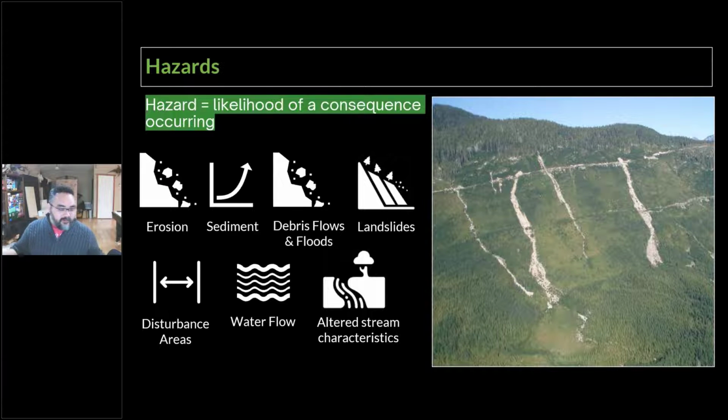So sediment, the things that are being eroded, is that sediment and the delivery to water courses. And that's not just accumulations in a water course. That can be accumulations in the road structures that we have, so in ditches or in culvert sumps, for example. So that's the sediment part. And of course, that feeds right into the debris flow or flood. And debris flows are basically, we're taking that sediment or increased peak flows and we're concentrating it generally into a channel or a gully.